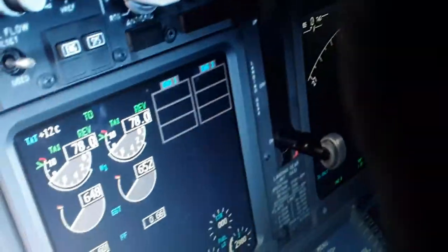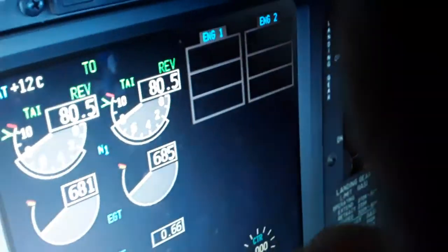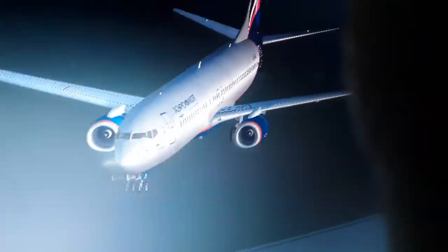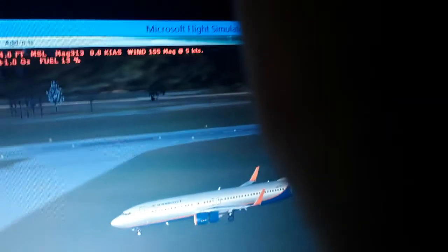Here's the thrust reverse. If I move this down and up into the idle and up, I engage the reverse thrust. You can see here we have the reverse thrust, 29.8% maximum, 8%. So you can see here the reverse blocker doors here. They're open. So this is gonna slow down the aircraft in flight.